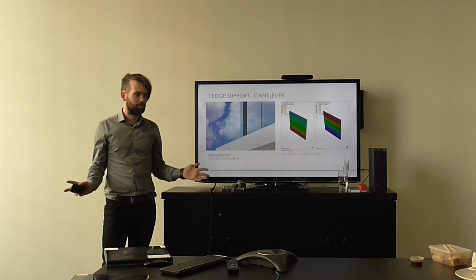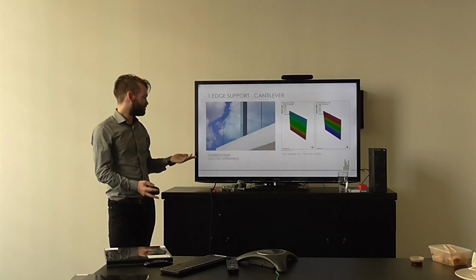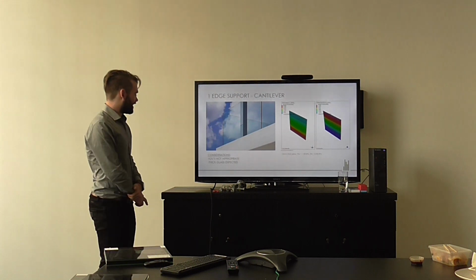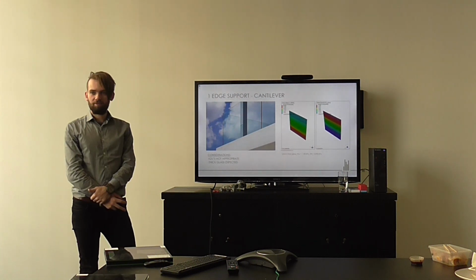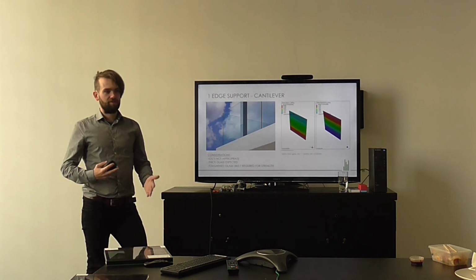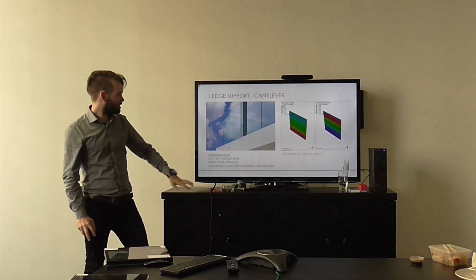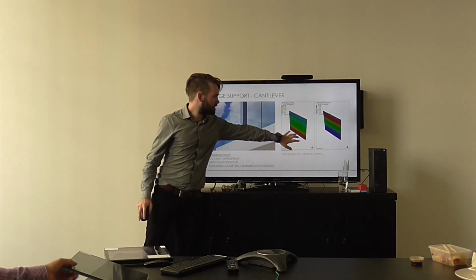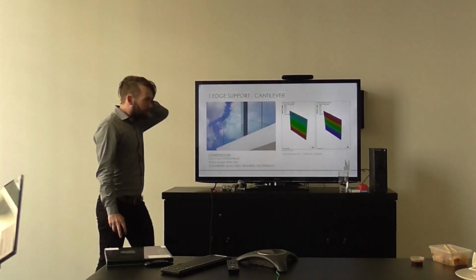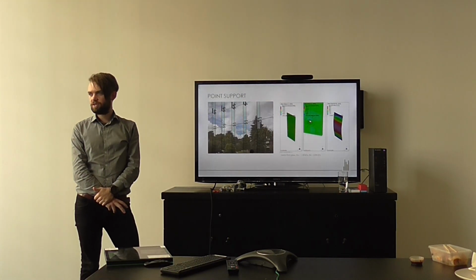Do not use IGUs in this application. You don't need them, first of all, but it's not a good idea. And then again, thick glass can probably be expected in some situations, and you're probably going to need a form of toughened glass, typically to deal with the high stress that you get at the bottom here, which is indicated by this mark.